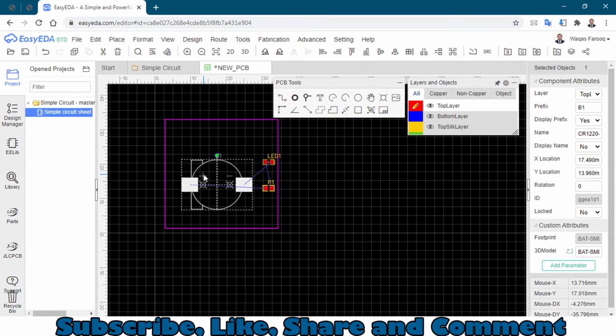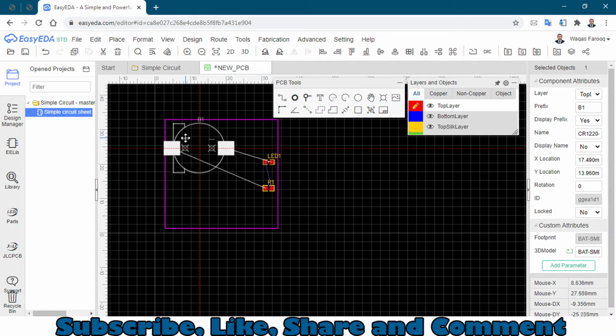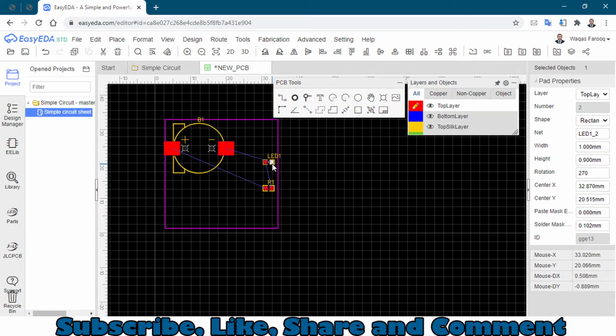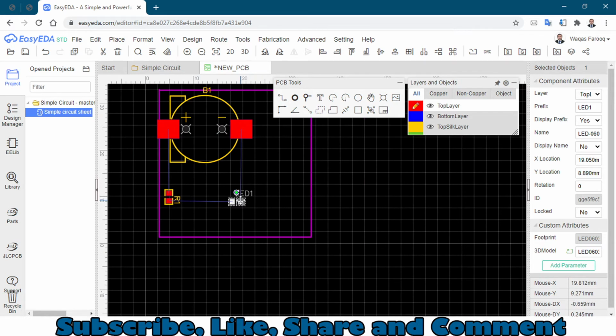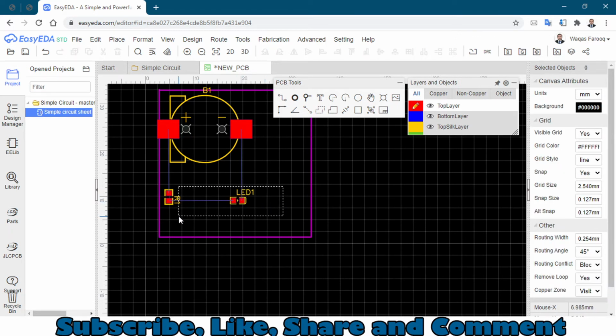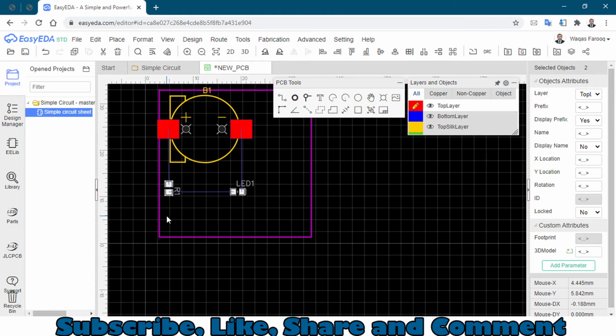So we have this battery. I will place this battery right here. We have the LED. I will place this LED here. We have the resistor. So this is not a proper way, so let's rotate by pressing R. You can rotate this resistor. I will place this resistor right here. We have the LED here. As you can see, now this is looking symmetrical. Let's just move this LED a little bit up, and we can adjust 2 components together by moving up and down.